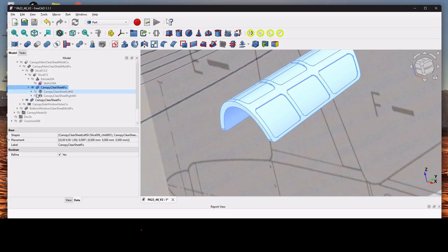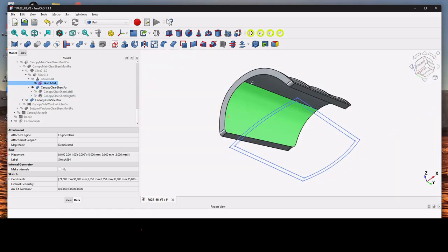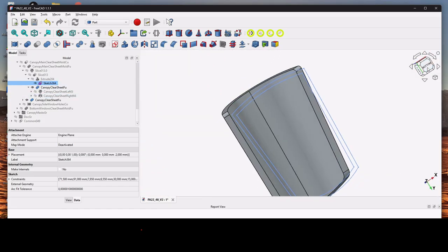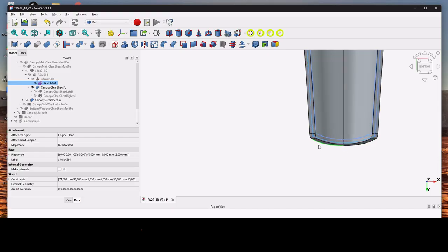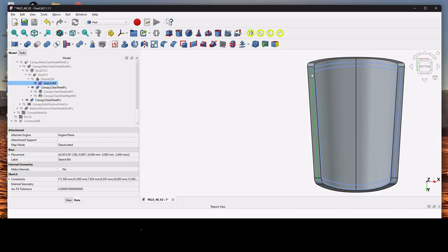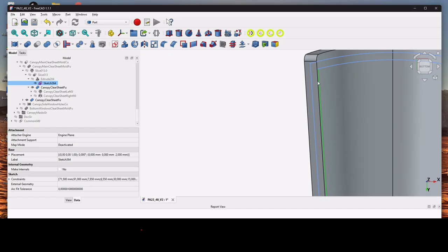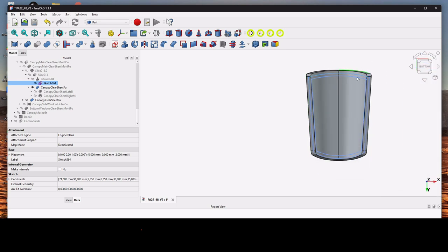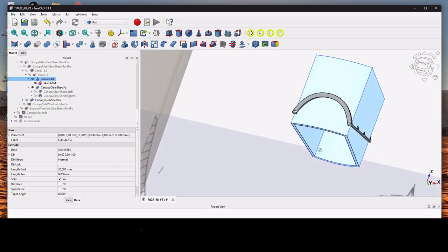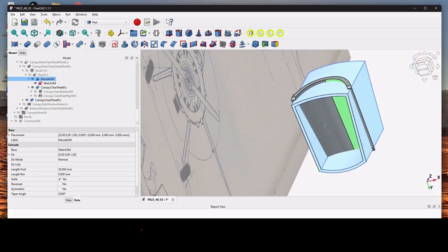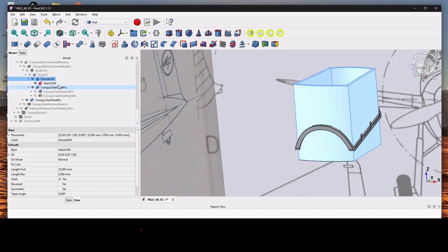Now what I'm doing is that I'm going at the bottom of that, okay, and I'm drawing a sketch that will be inside this 1.4 mm minus 0.3 mm, so 1.1 mm. And I'm just drawing a sketch by hand in order to have the contour of that. What that allows me to cut, I would say, and to have the basis of my mold in a way.